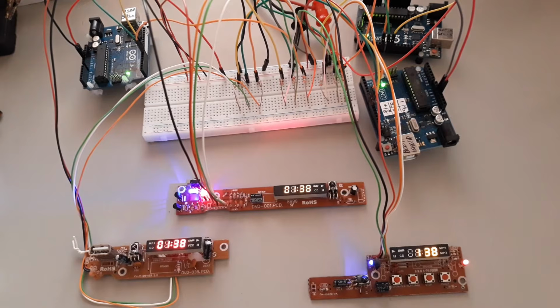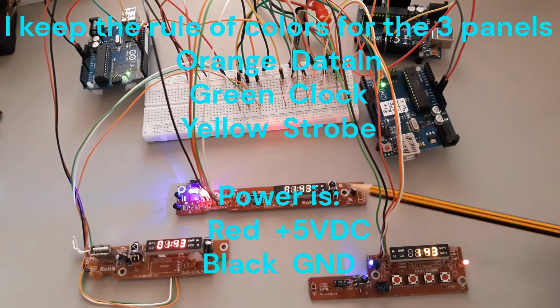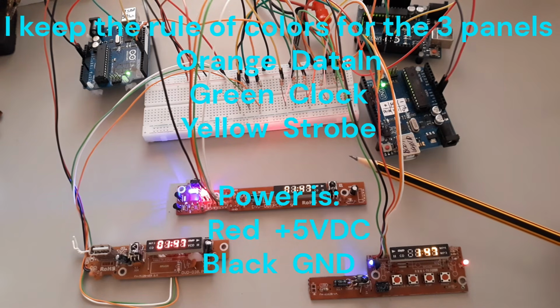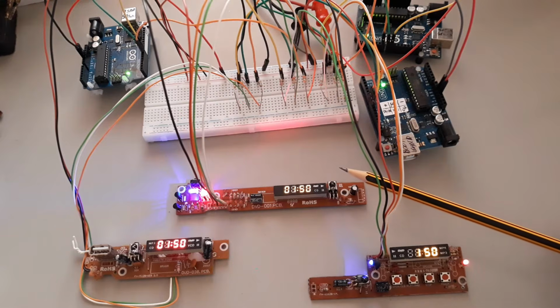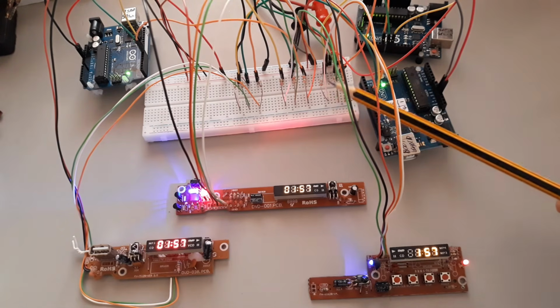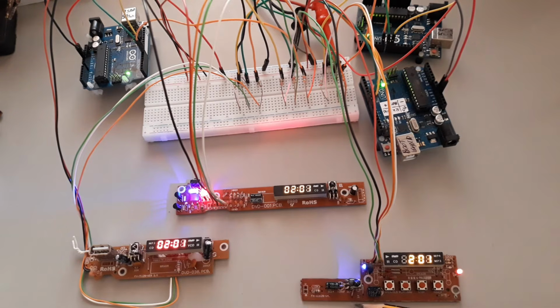The connections I have made to each panel are 3 pins for the communication. In this case they are data in, clock, and strobe. Because the power source of all the panels and the Arduino is the same, the reference is already created, okay? The GND is the same in each element of this setup, okay?